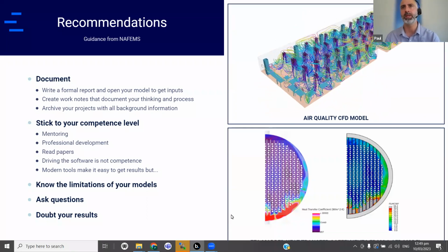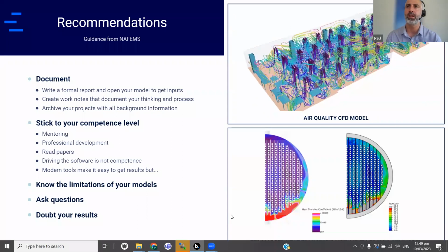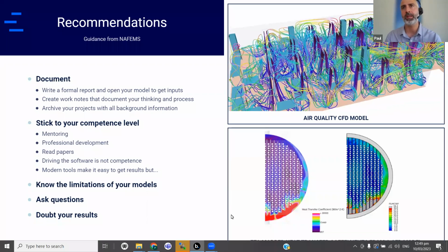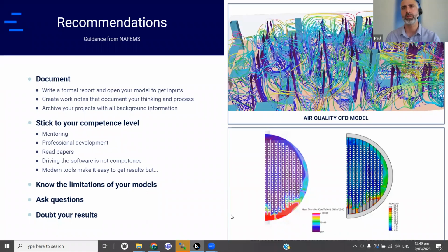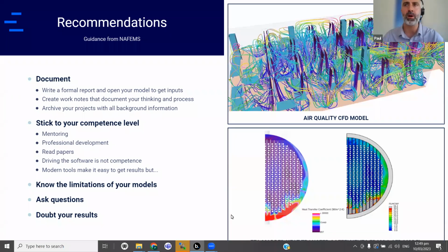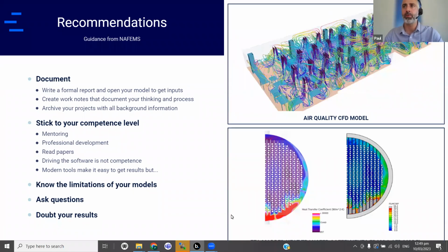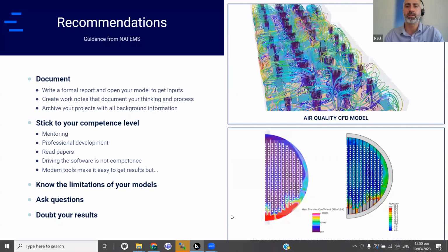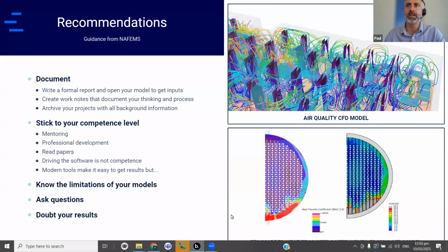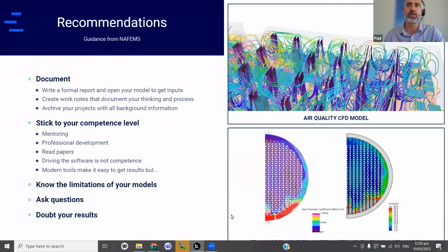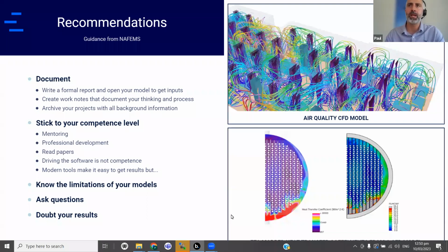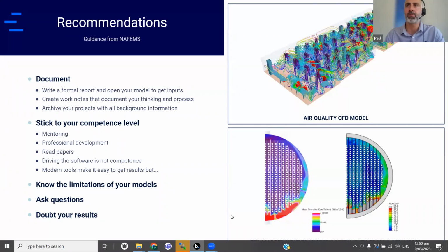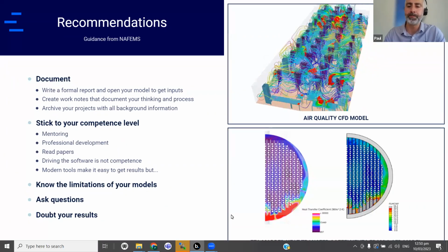For example, in wet wells you can have vortex cores forming, free surface vortex cores forming, and it's not always obvious that those are going to appear, and they could be caused by the shape of dividing walls or the shape of the wet well. And sometimes some changes to the geometry of the wet well are required to improve flow into the intake and to remediate some of those vortex cores. So CFD, when it's done properly, can allow you to understand and document risks associated with those issues.